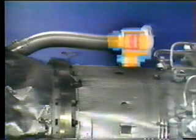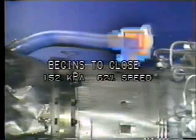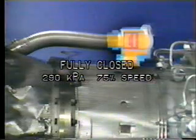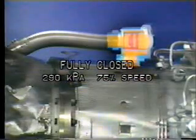As you can see in this illustration, the bleed valve is held open by a spring, allowing the excess air pressure to flow out of the combustor. The pressure inside the combustor increases with engine speed and eventually forces the bleed air valve closed. All of the air entering the combustor is now forced through turbine nozzles and rotors and out the exhaust bellows. The valve begins to close at about 152 kPa, which is about 62% engine speed, and closes completely when the pressure reaches 290 kPa, which is about 75% engine speed.